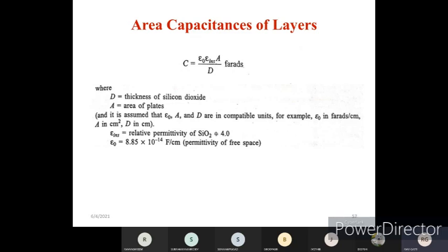On top of this, we again deposited silicon dioxide, and after that we deposited a dielectric, and on top of that, for the gate terminal, we deposited polysilicon. So in each layering architecture, we either use silicon dioxide to sandwich between the two layers, or we use a dielectric material.